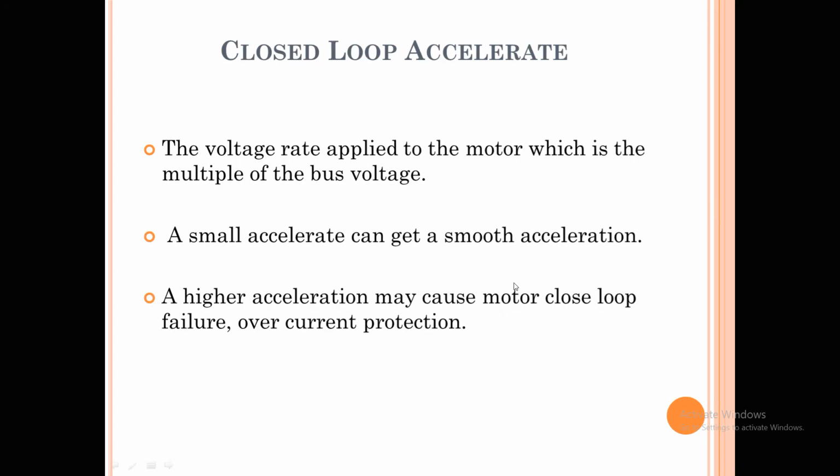Okay. Now we have switched the motor operation to the closed loop. Now you need to increase your throttle again, because while choosing this one you reduced the RPM. So you need to select the closed loop acceleration, so that it will rotate your motor. When your motor is now operating in closed loop, you need to provide a closed loop acceleration to the motor.